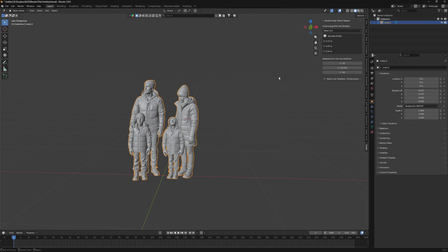So now here in the add-on, I see how tall they are. Okay, I always have to look for the size. It's Y. If I want it to be the Z axis, I press Control A, rotation and scale, and now the height is along the Z axis. So this is something you have to do: Control A, apply scale and rotation.